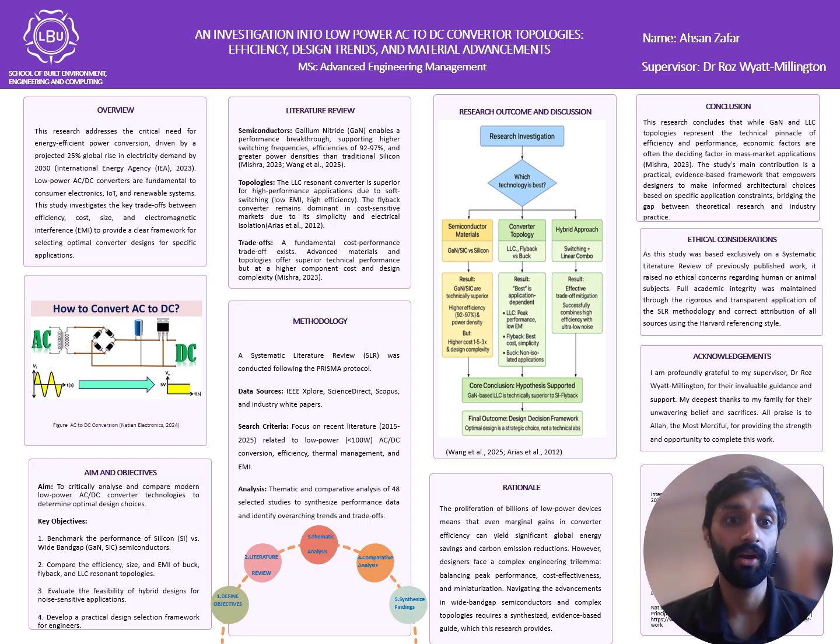Hybrid designs were found effective in sensitive systems. They combine the efficiency of switching converters with the low noise of linear regulators, which is very useful for medical and audio devices. These results confirm the main hypothesis: a GaN-based LLC resonant converter performs better than a silicon-based flyback converter at 15 watts. The only trade-off is that GaN-based LLC designs are more costly and more complex.